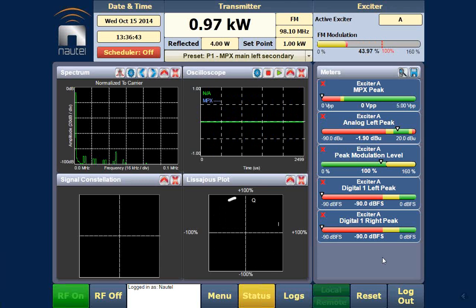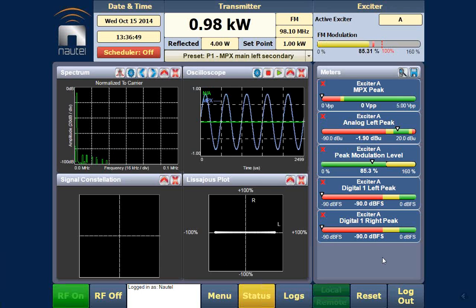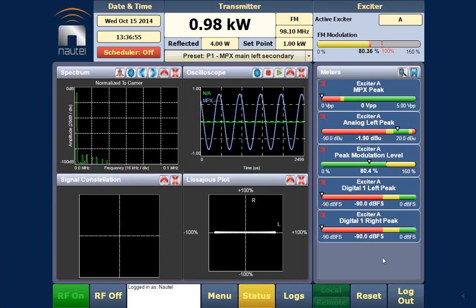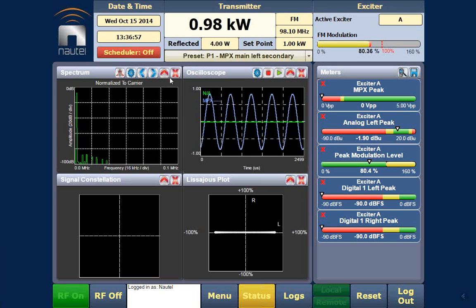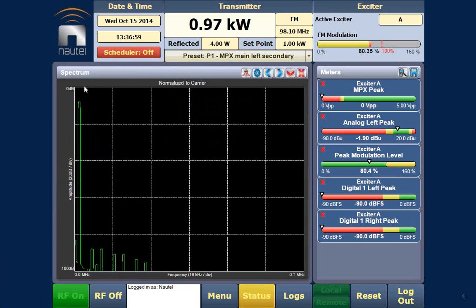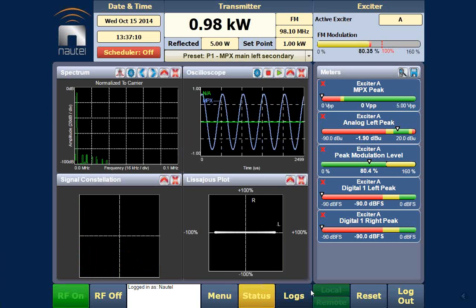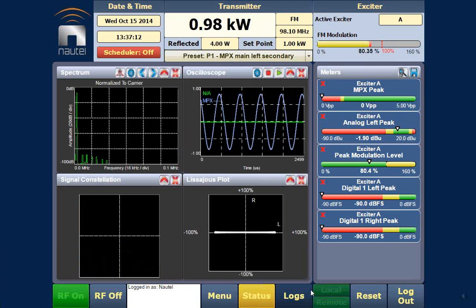Okay. So now we've lost our MPX. And in approximately 5 seconds, we're going to come back on at twice the frequency because we're actually running with the left. The frequency here into the oscilloscope, but you could also take this full screen and you could see by going to here, like that 2 kilohertz is now the frequency. That's our left input with a slightly reduced 80% modulation depth. Oscilloscope, again, gets updated easily.